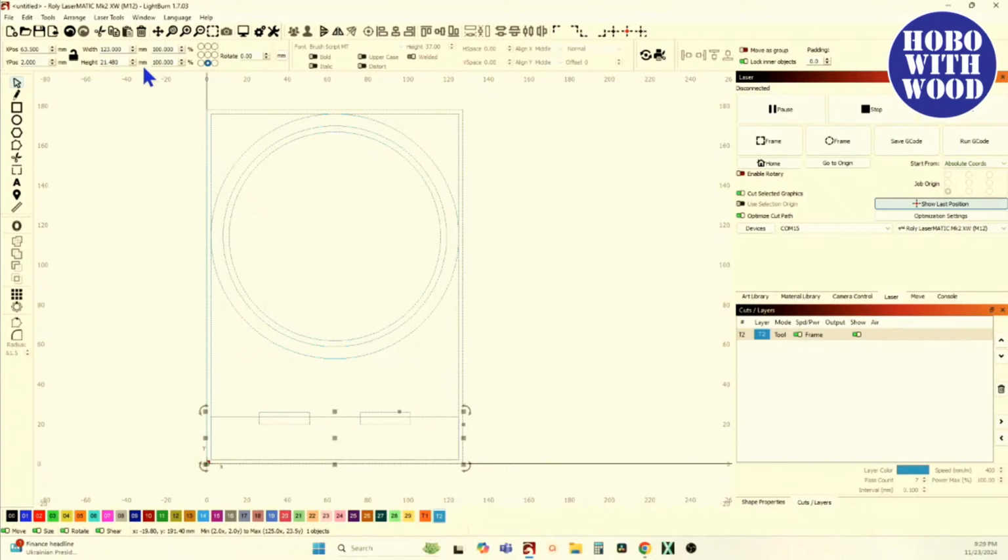The material is 6 millimeters thick, and I want 3 times the thickness of the material on either side, which is 18. 18 twice is 36, plus 6 is 42 millimeters. So with that anchored at the bottom, I'm going to tell it 42 millimeters. That puts it there. Now I'm going to select this pair right here, hold my shift button, select this rectangle and tell it to go to center. And now those are centered up there. Now if that's 42 millimeters, how high is this rectangle?